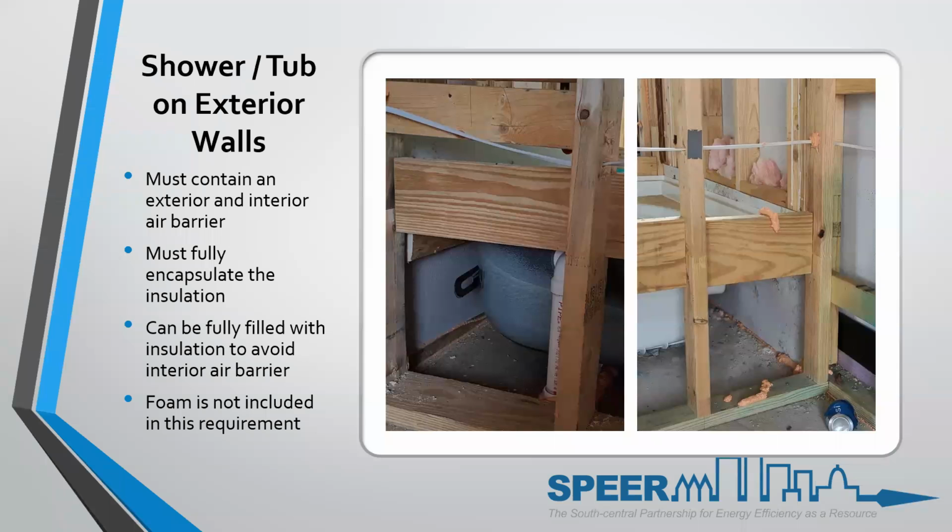Brad says, in that scenario for multifamily, does the gypcrete above the apartment work as an air barrier? You'd have to look at its air permeance to see. I'm pretty sure gypcrete is and can be considered an air barrier, but I would have to look at the air permeance of that. I'm pretty sure that it still is, because sheetrock is an air barrier, but it's vapor permeable. I believe gypcrete is the same way. It is an air barrier, but it's still vapor permeable. So I'm pretty sure that does meet the intent.